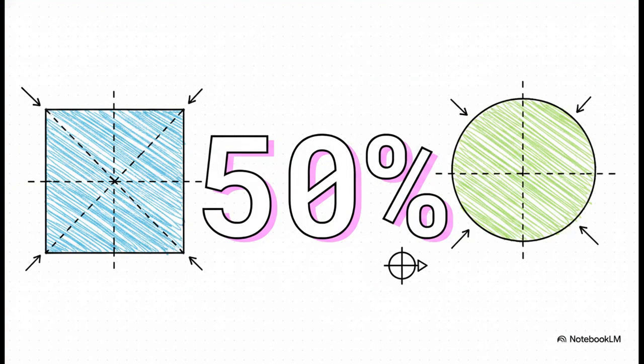Here's a huge benefit for production. Using geometric dimensioning symbols like position can actually allow for more than 50% greater tolerance zones compared to traditional linear dimensioning. Because you are using a cylindrical zone rather than a square coordinate zone, you capture the functional area in those diagonal corners that a square would just automatically reject. Mathematically, this actually gives the machinist over 57% more functional tolerance area to work with.